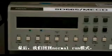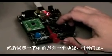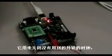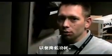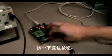So the last thing we're going to do is get back into normal run mode, and we're going to show you a feature on the QE8 called clock gating. What this does is it basically shuts off the clocks to any unused peripherals, so that we're lowering the overall chip power consumption. So I'm going to do that by hitting the reset button here.